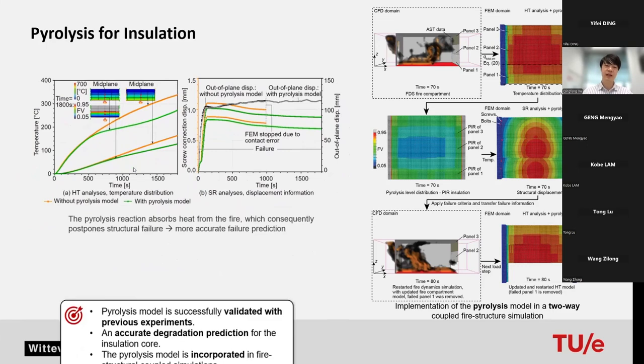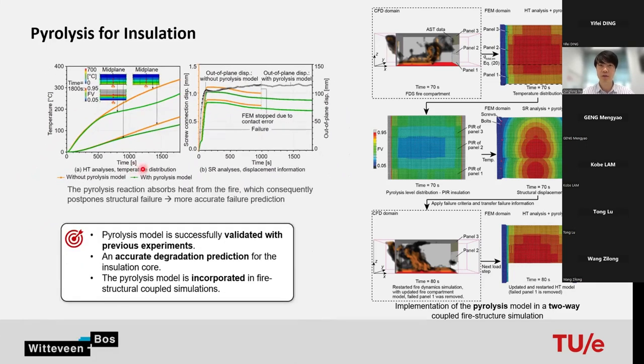So to put it all together, in the third part of my PhD, I developed a pyrolysis model, and I successfully validated it with previous experiments, and the results show an accurate degradation prediction for the insulation core. And the pyrolysis model is also incorporated in the fire structure coupled simulations.